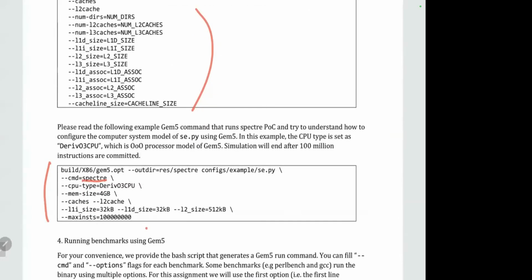I recommend to use the Docker image for running gem5. If you use the Docker image, then you can set the same execution environment for running the architectural simulator. Also, you can use the same image file and run multiple containers using the Docker image, which means that you can exploit the multiple cores on your machine.